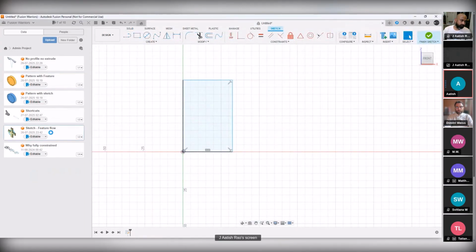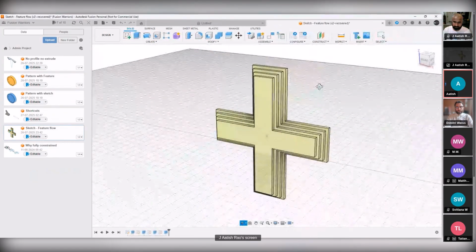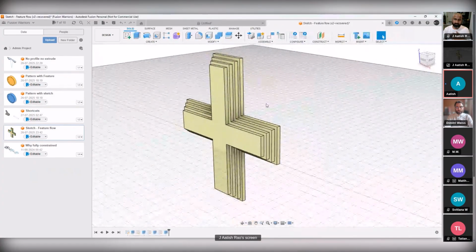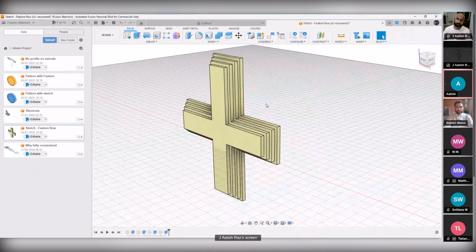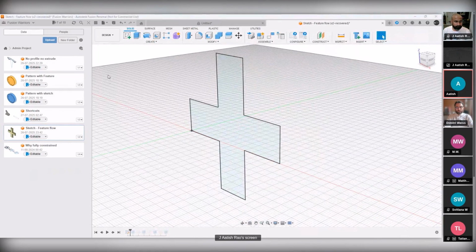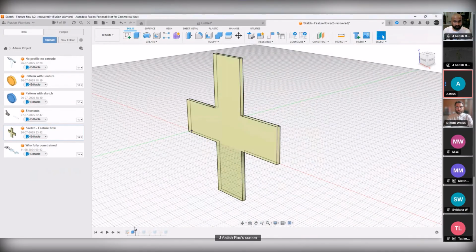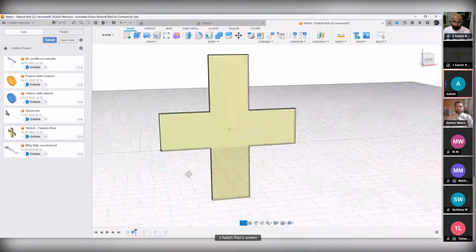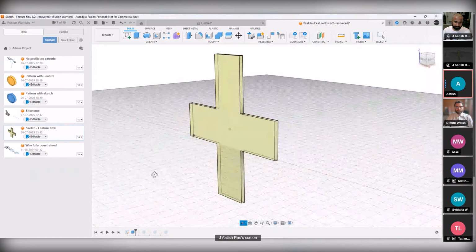Next is the flow of sketch to model. As you can see here, it's a stepped geometry. So there are certain layers of extrusion going on, certain layers of push pull going on. In this case, initially we started with a sketch, and after that, over that sketch, we used the push pull tool or the extrude tool, and we created this particular 3D geometry.